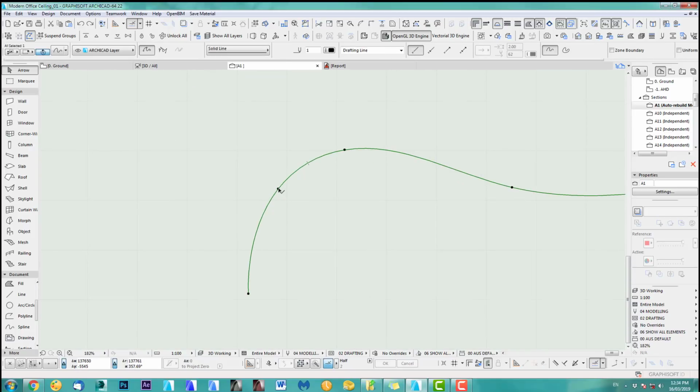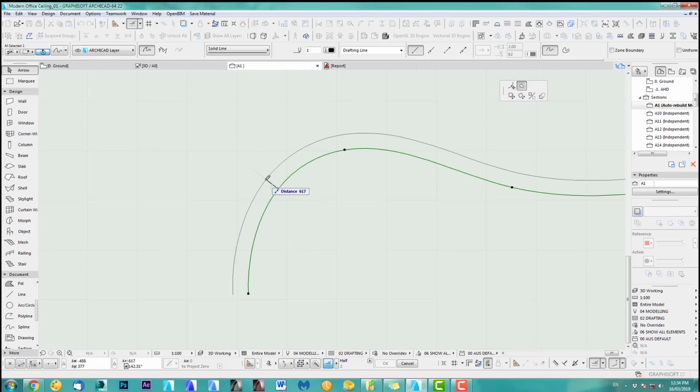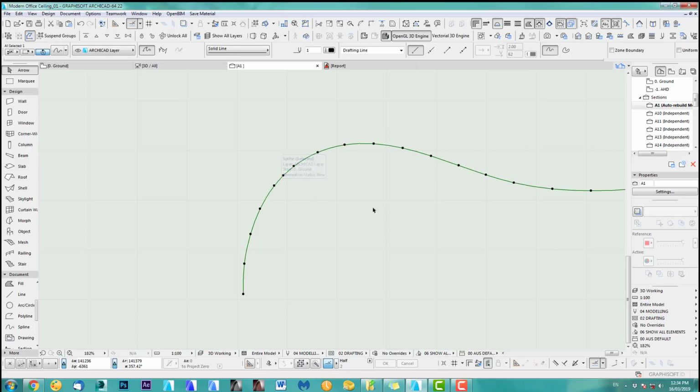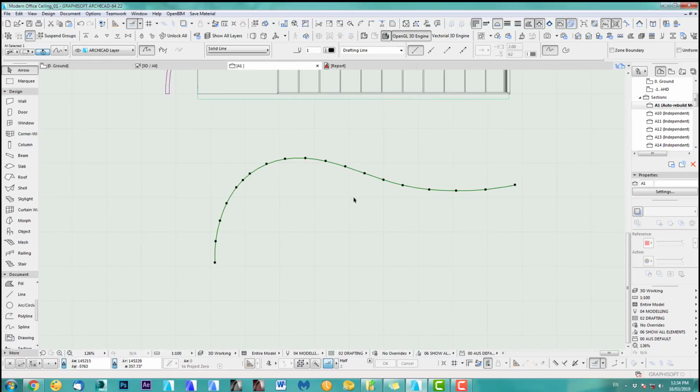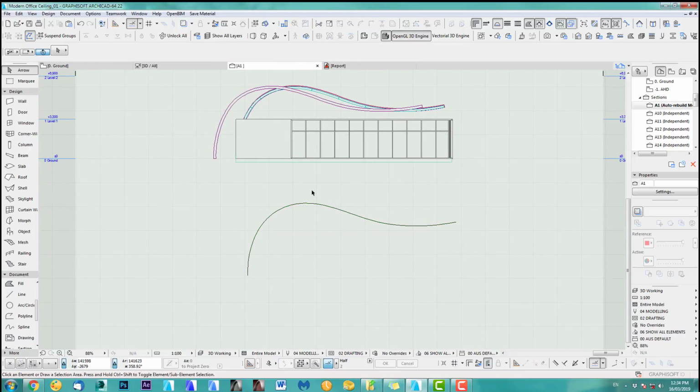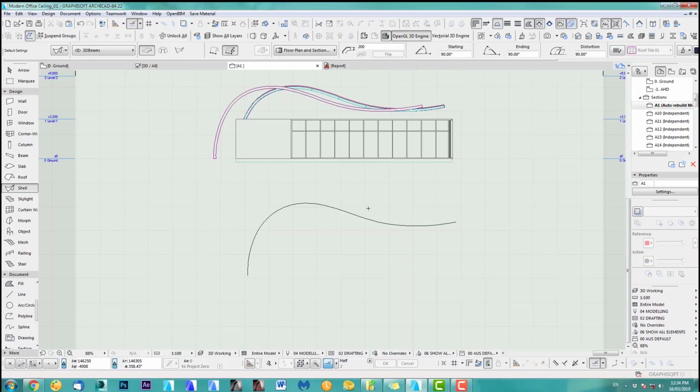Let's just click in here and we should be able to offset. Yeah, that looks good. 200. Okay, that's an interesting one. It adds some more polygons. I haven't seen that before, but you know what? It still looks nice and smooth. I'm happy with that. Now, obviously, I can take this one, space click, and we sweep again.